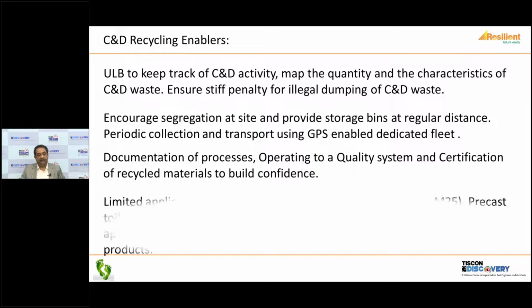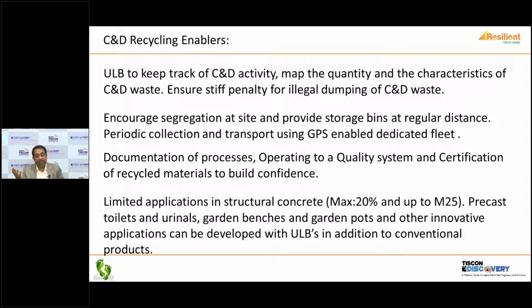And finally, when you look at this, you know that up to M25 and up to a maximum of 20% is what can be used in concrete. So we need to look beyond concrete, at materials like precast toilets and urinals, garden benches, garden pots. You have to really think out of the box to see where we can use it in non-structural applications. And this is extremely important together with use in conventional products like your bricks and blocks.